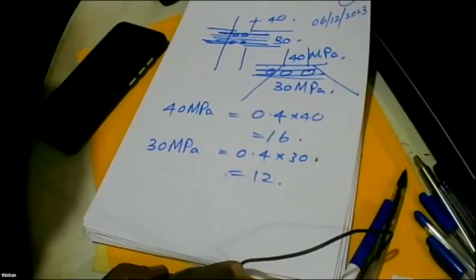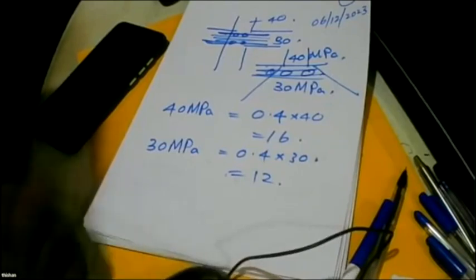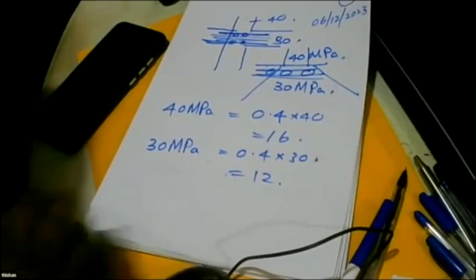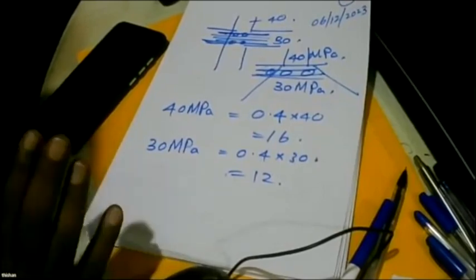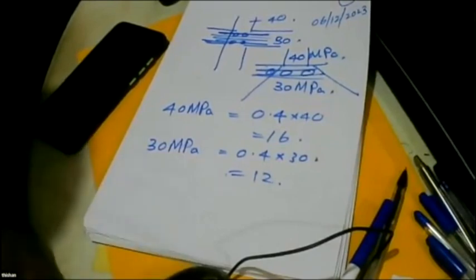That's why I showed you how I manipulate the numbers. I know only two things. One is cement is the friend. What is the enemy? I manipulate the enemy. The moment I manipulate the enemy and make it as small as possible, I can bring the cement content down in a drastic manner.